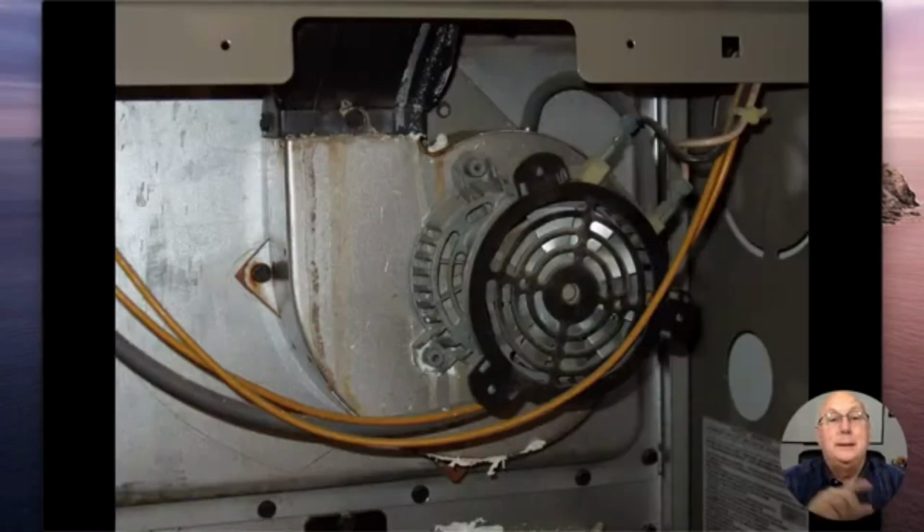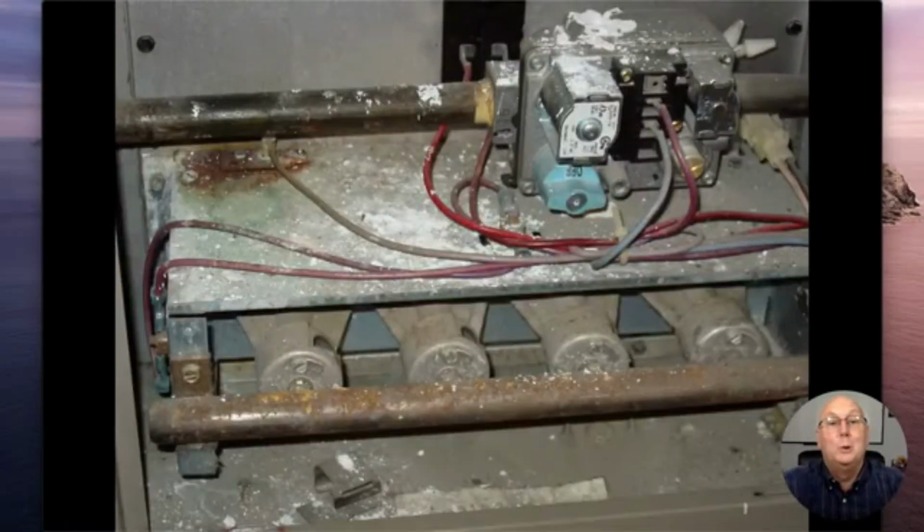Now we get up here and we start seeing the rust stains and the white condensation come back in here. You could actually see some dripping on the very bottom underneath here as well. And so it's actually leaking out of the inducer fan. All that condensation's coming back. This furnace is not venting properly. I should not have that condensation coming in here, and I don't want to take ownership of this problem. We're going to document this, and we're going to push this off to a heating contractor. Same thing, more corrosion, more rust, more dripping. These are all things that we're going to be pushing off to a heating contractor.